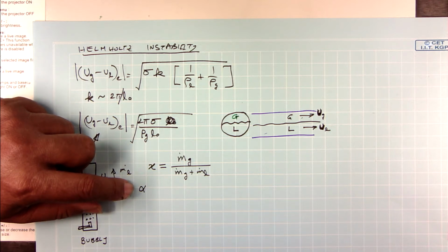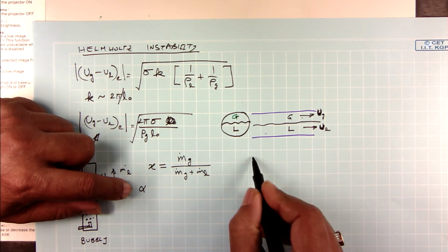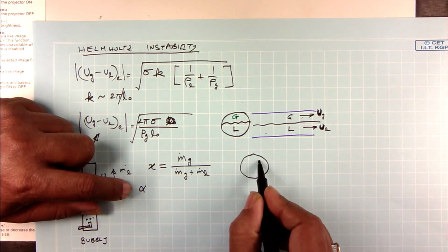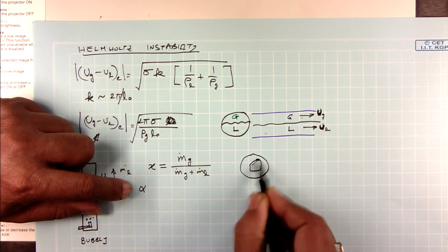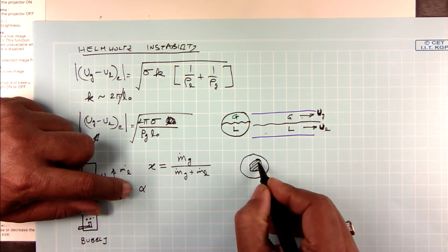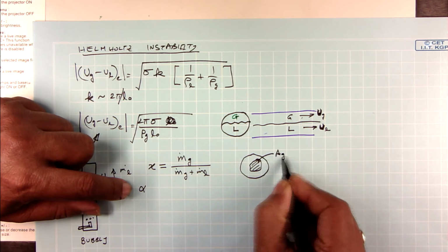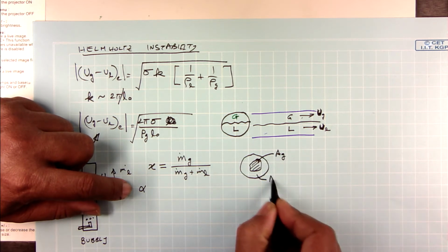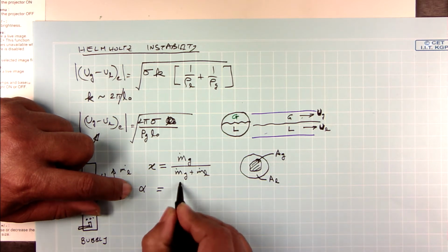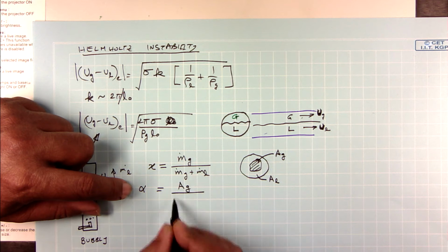Okay. Now with respect to the metrology technique for the void fraction, your definition of void fraction changes. But the most fundamental definition of void fraction is: if I take a pipe, and a part of the pipe, if I take a cross section at any location, and if I can measure the area occupied by the gas versus the area occupied by the liquid, the most fundamental definition of void fraction is Ag divided by Ag plus Al.